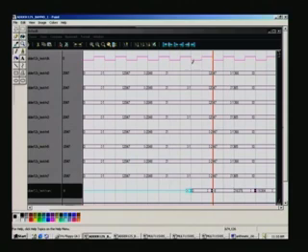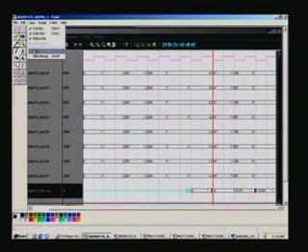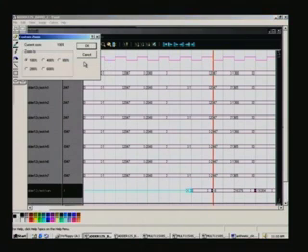So, after 5, after a further delay of almost some 5 nanoseconds or more, the result manifests here. This is because of back annotation. Actually, without back annotation you should have got it right at this edge. Because of back annotation, gate delays come into the picture, and the result appears only after a delay, and clearly it is after the 5th clock pulse, and that is what we had designed for. We will zoom it here and see what the results are.